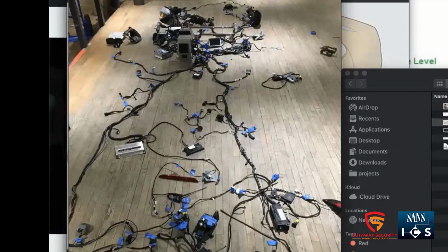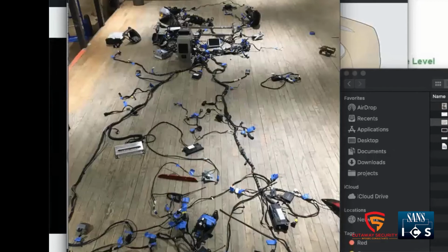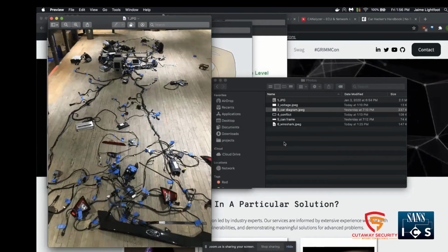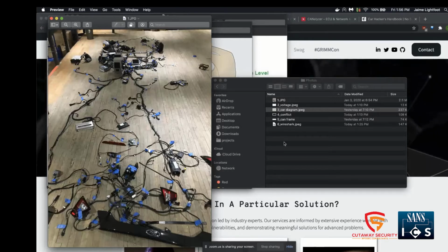Instead of thinking one arbitration ID per device or per ECU, think one arbitration ID per type of message from an ECU. So ECUs can send out these CAN messages with different arbitration IDs. Maybe the engine has an arbitration ID that it uses like a category for the most important messages that need to be acted on right away. It might also have more informational, less urgent messages, and it would send those out over a different arbitration ID. So the devices are all listening on their shared bus. There might be segmentation. We'll talk about that later. And if the bus isn't busy, if no one is currently talking on the bus, then a device can start a message.